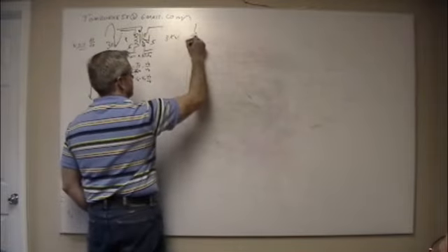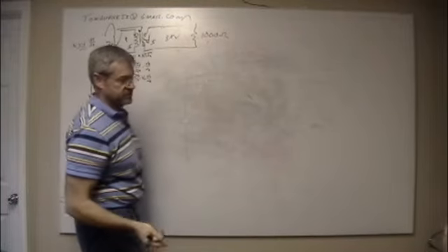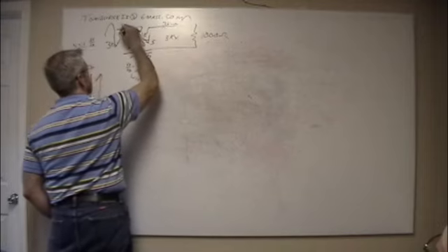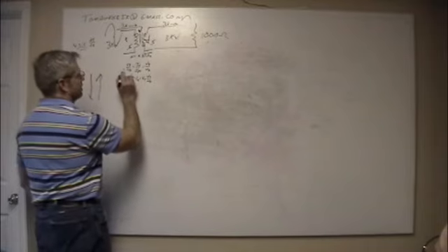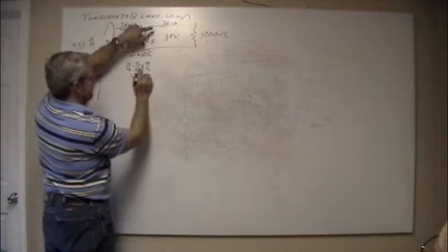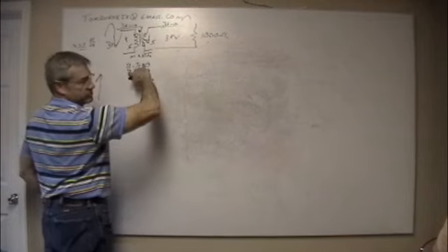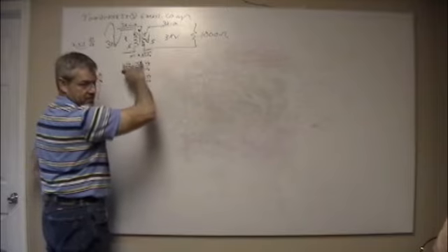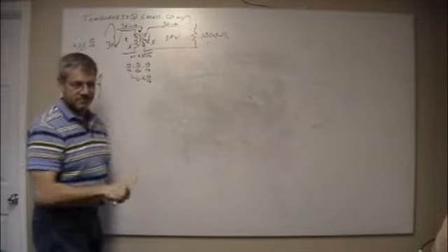And if I put this on a load that's 1,000 ohms, just to keep numbers easy, this will be a 3 amp circuit there, and that'll be a 3 amp circuit there. V primary divided by V secondary is equal to I secondary divided by I primary. Power equals power, IV times IV, power has to be maintained, minus any losses. You're going to have some losses.